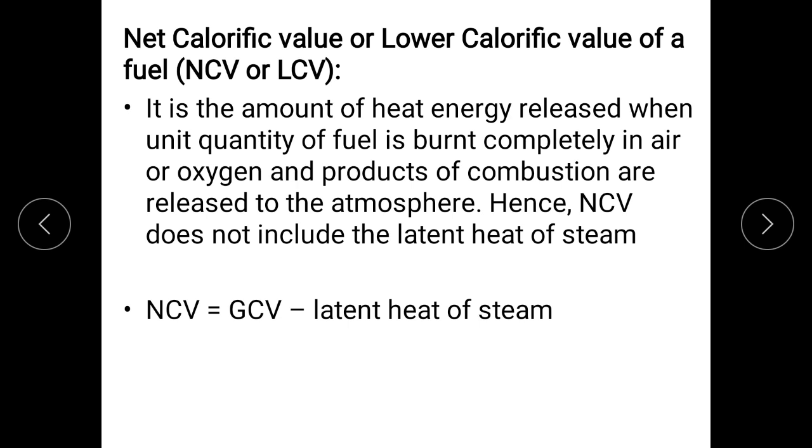As a result, NCV does not include latent heat of steam. Since products are completely released into the atmosphere, you don't get condensation, you don't get latent heat of steam due to the condensation of steam. Therefore, NCV does not include latent heat of steam.